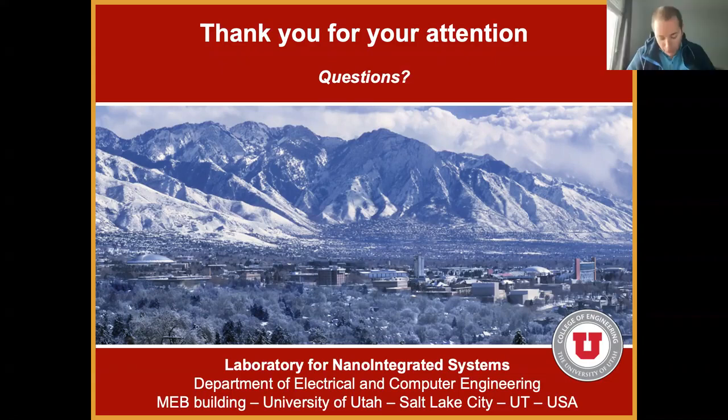Yeah, good question. Thank you, Rose, for asking that. So it really depends on your use model, on how you approach your CGRA. I would say the VTR portion is probably good enough, because it will just be up to you to restrict your XML architecture for your CGRA to make sure you route whatever signals from output A to input B or stuff like that. In other words, let me just go back there real quick.